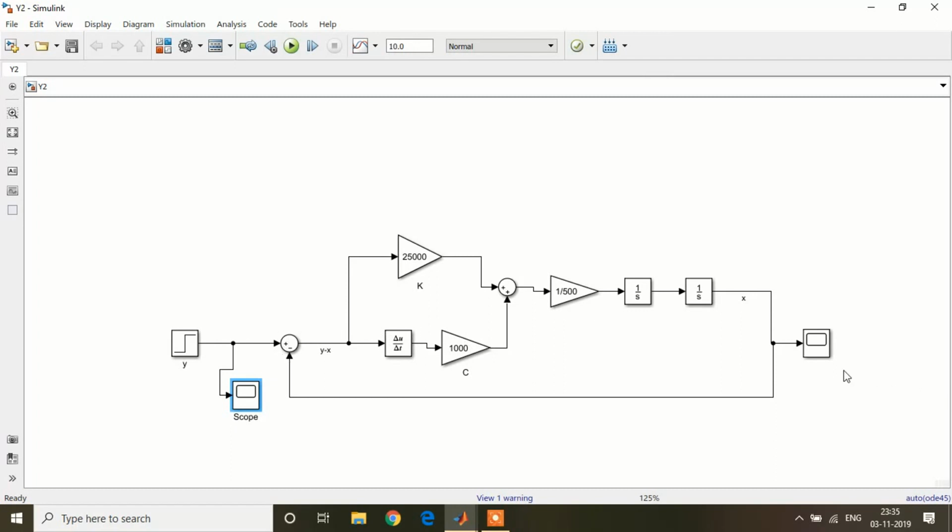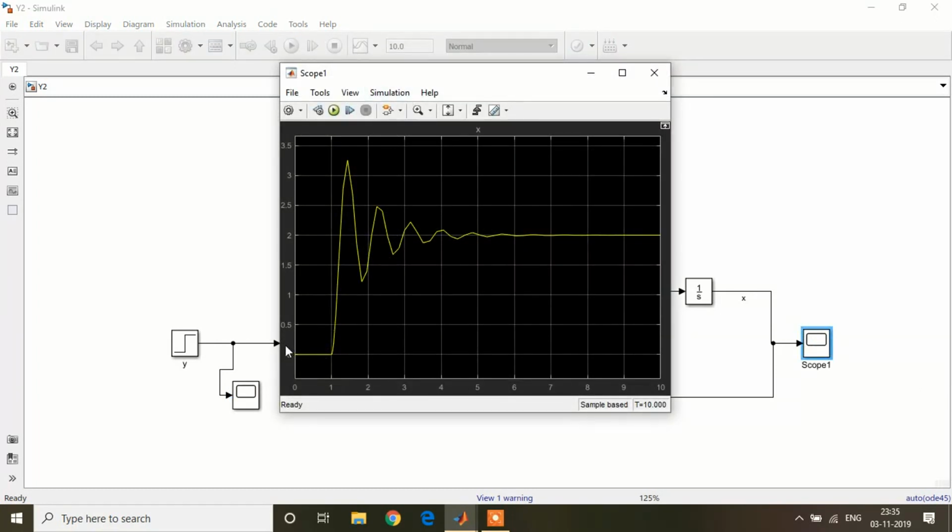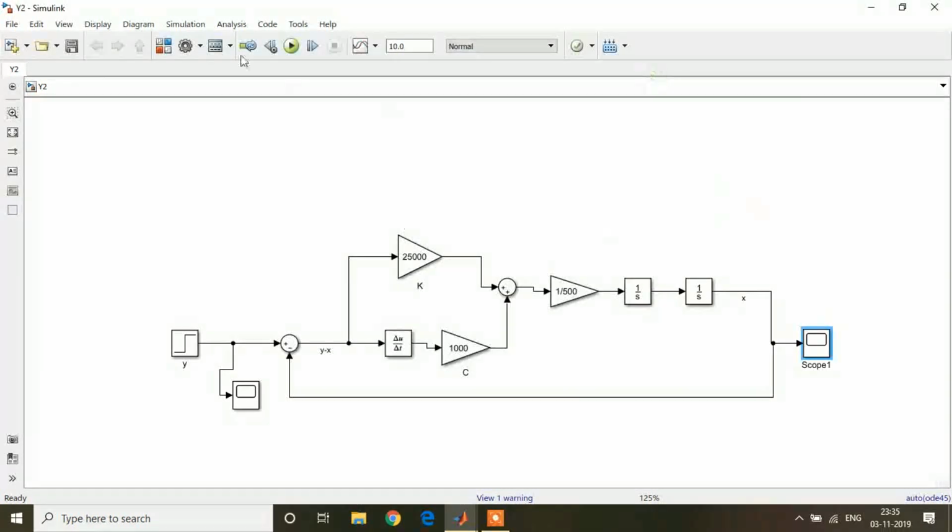As soon as the bump of 2 is given to the wheel, firstly it goes up, and because of the stiffness and dampers that are there, it damps out at around 7 seconds. The times can be adjusted accordingly.